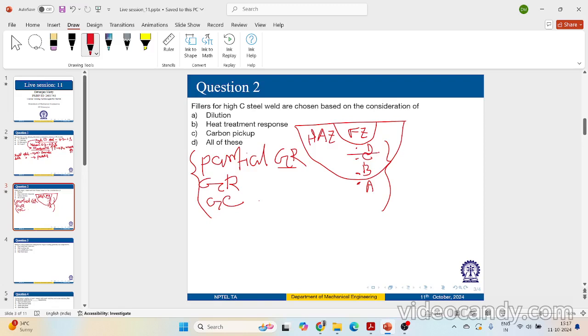So position D is the grain coarsened region, है ना? Which is the most vicinity of your fusion zone. So over there you will experience high cooling rate or low cooling rate. In terms of cooling rate, over there, because the temperature will be much higher, because that is in the vicinity of fusion zone, right? So it will experience higher cooling rate. My position D, it will experience, so CR is cooling rate. Please remember these abbreviations, or you can note these abbreviations. So cooling rate will be much higher for position D, right?